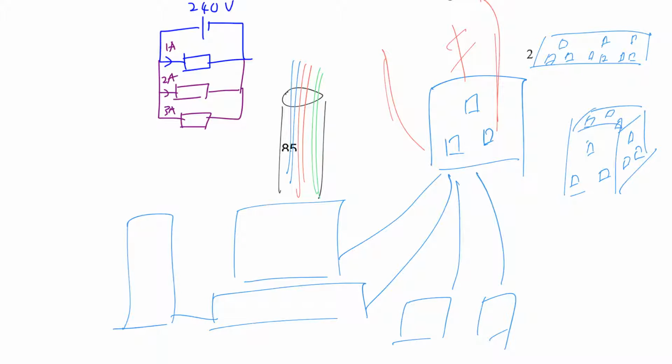But in our modern households, you have a circuit breaker, you have these whole panels of circuit breakers. Remember, in your house you will see something like this. Got a lot of these that you can reset if one trips. So what will happen is, if it shorts, that means if the live and neutral wire touches, then it will trip because the current is too high. You understand that? But it will not trip if it starts to melt yet. Until it melts and touches, then it will trip.